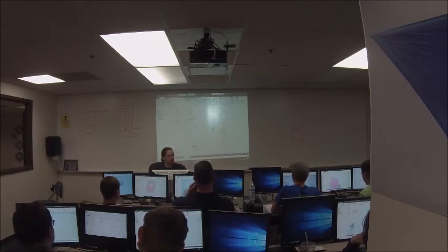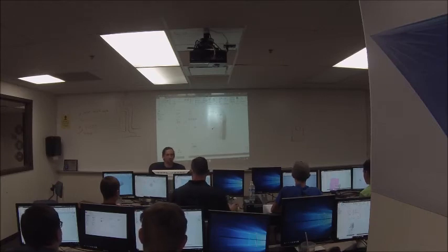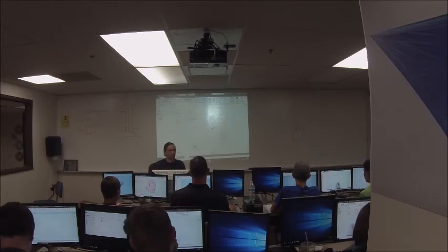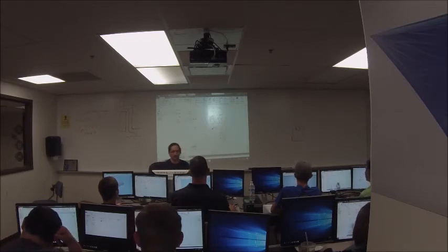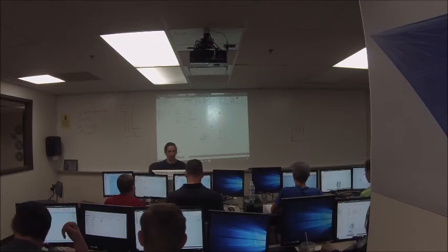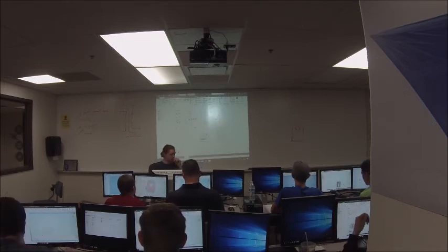Hold the control key down, and then you can hover over them again and click on the one you didn't mean to, and it'll remove it from the extrusion as well. So I can sit here and hold control and take it away and add this one to the extrusion, and now I don't want that, hold control and click that one. So play with that a little bit, get used to how that works.